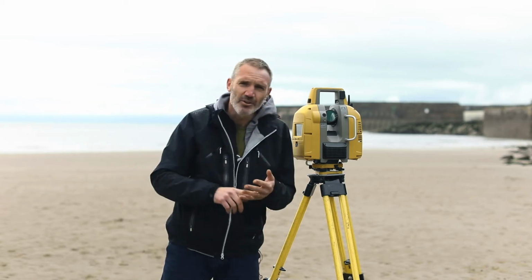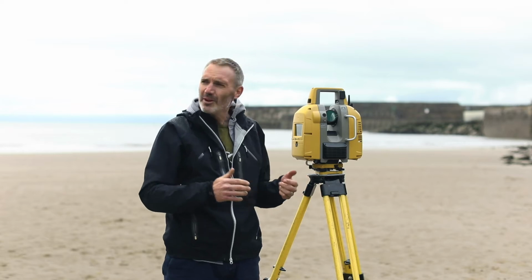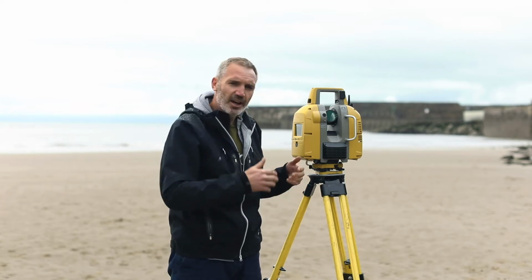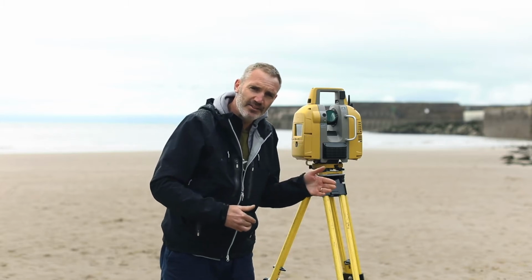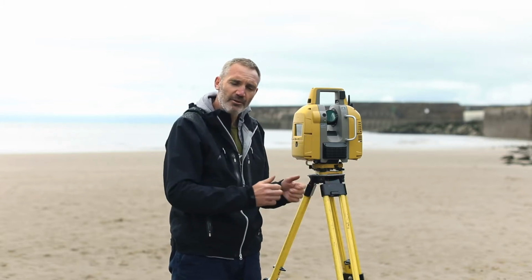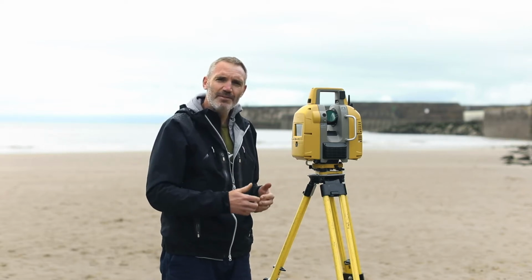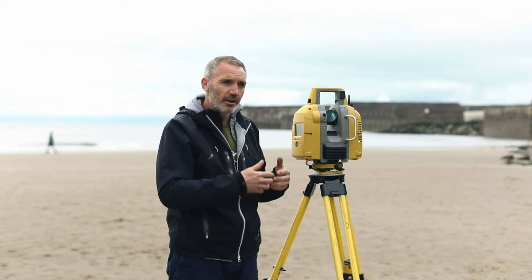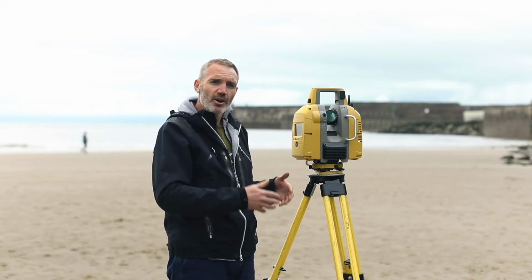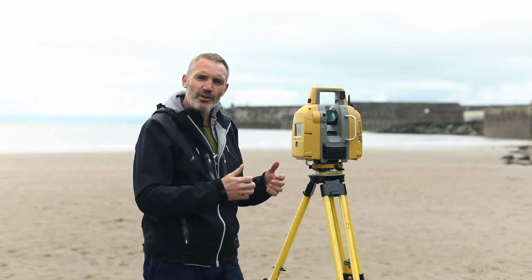And that imagery is a useful visual record for where this survey point was, but it's also used to colour the points. So we can have points either coloured by the intensity, which is the amount of light they reflect, or we can colour them by the true RGB values, as we call it. So this will look really like virtual reality, very realistic once we look at the 3D model in the viewing software.